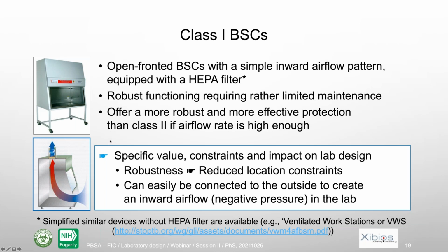It is very interesting because it's very robust. It's a simple process. The airflow has one direction, it's very clear. And because of that, there are not so many constraints with respect to location. You could put it in different places, even if they don't appear as the most favorable. Also, you could connect a duct to the outside, going out of the lab. In that case, you will ventilate the lab and you provoke a negative pressure very easily, actually.